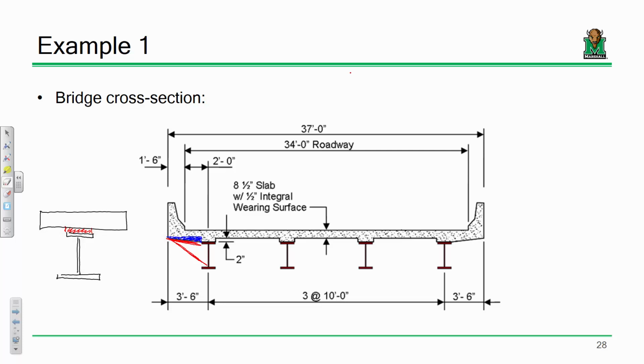So you see what I mean? In its finished state, the moment of inertia is bigger. The loads are bigger, but the moment of inertia is bigger also. So during construction, you might get a worse stress than you do in the finished state. Does that make sense? But to go to your specific question about the equipment, the bid well, the screeding rail, all that, yes, absolutely, you do need to account for it. But not in the finished state, that's only during construction.